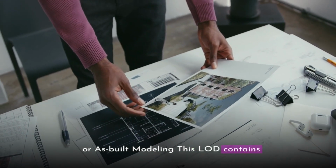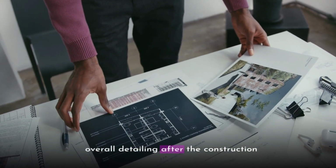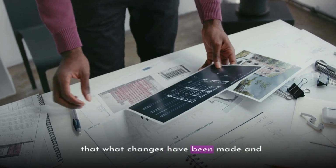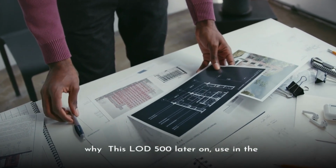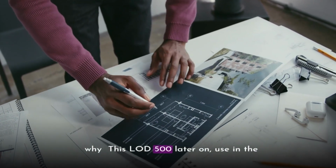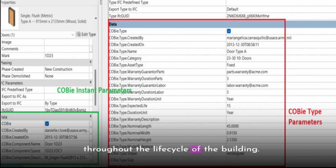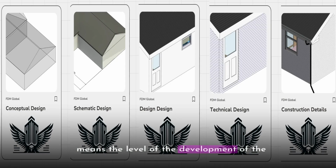This LOD contains overall detailing, from after the construction has started to the completion stage, of what changes have been made and why. This LOD 500 is later used in the maintenance and operational management throughout the life cycle of the building. This overall concept is known as the LOD in most of the standards of BIM. LOD means the level of development of the model as per the particular detailing required at the construction site.